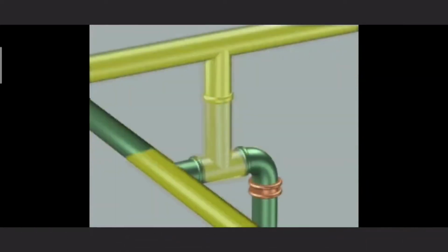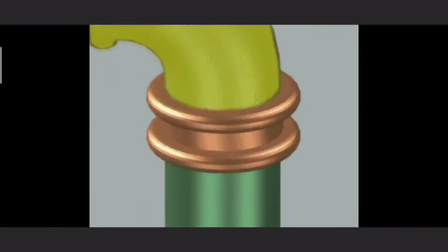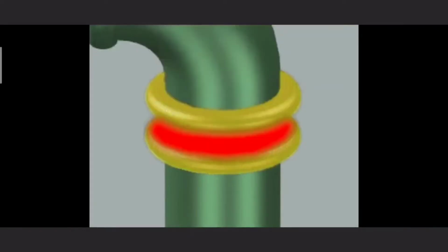Each burst travels through a closed switch and charges a capacitor. The turned-on capacitors represent the ones. The uncharged capacitors are considered zeros. Because all capacitors lose their charge over time, bursts of electricity continuously flow to refresh them.